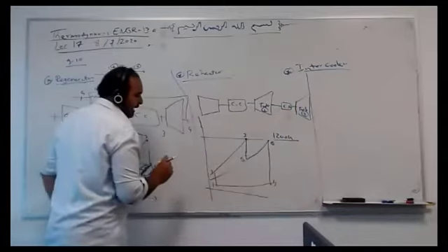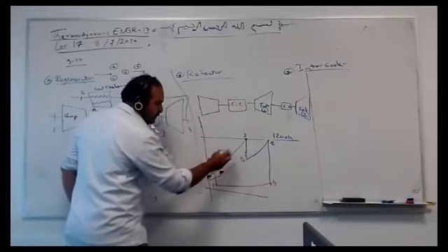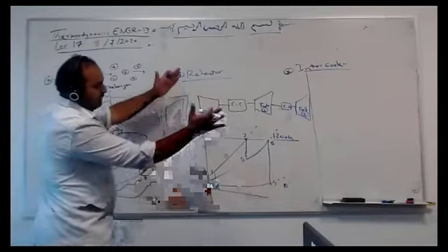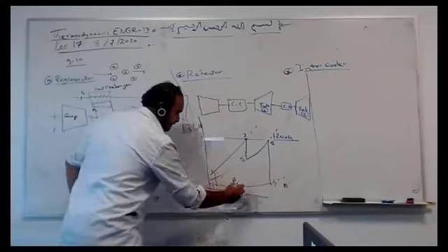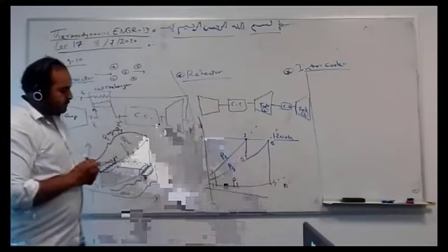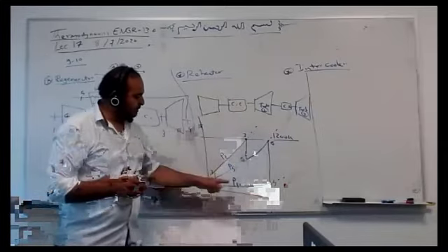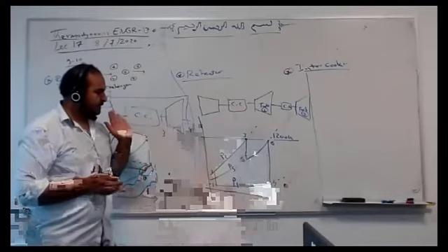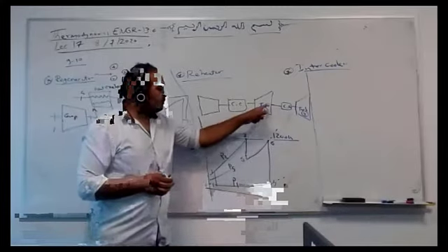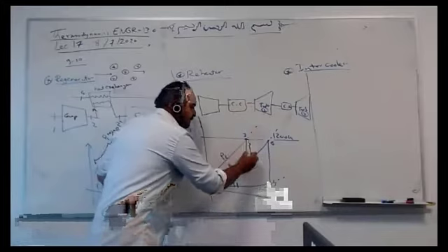So what happened here? I cannot go to a higher temperature, but I assume here we have 3, 4 constant pressure lines. They are diverging, all of them diverging. Pressure 1, pressure 2, let's say pressure 5. This is 1 and 4 the same. 5 and 6 is the same. 2 and 3 are the same. I call it P1, P5, P2, for example. Then I compress from 1 to 2. Then I burn. I cannot go too much. I only go here. Then I expand in turbine 1. This is turbine 1.